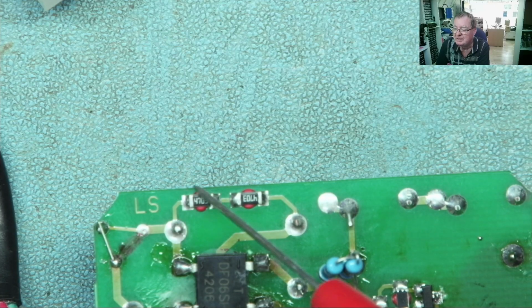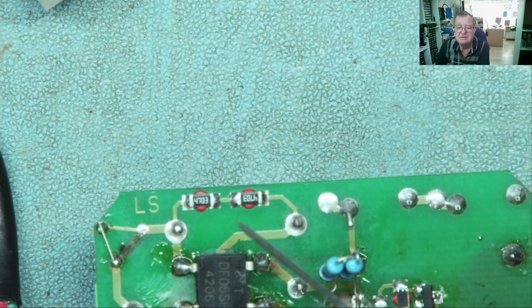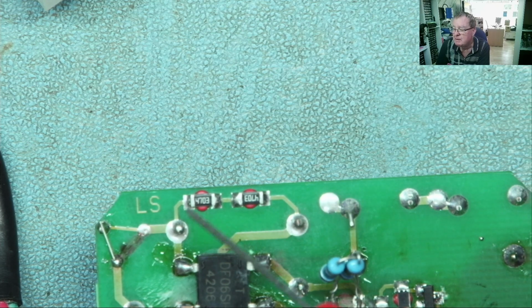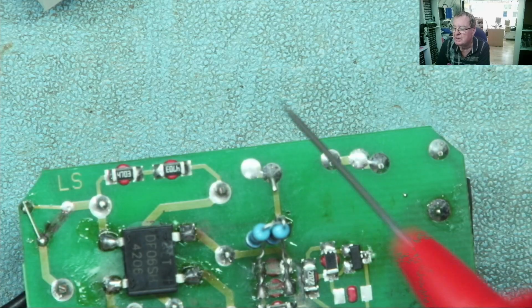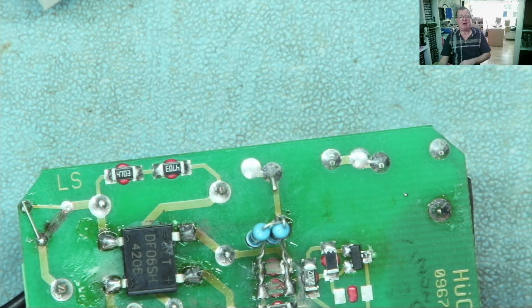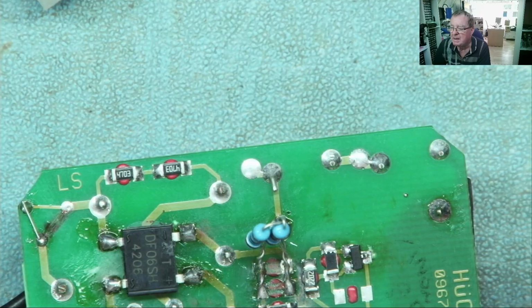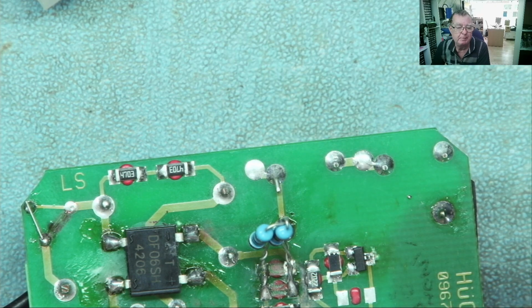So 470,000 in series with another 470,000. So that's 940,000, almost a megohm. And you often find 3 or 4 in series, and they may be higher value than these, 1 meg or more. These sort of resistors in switch mode power supplies are part of the startup sequence, which powers the power supply up when you first apply the mains. And those resistors have a habit of just giving up. It may be intended as almost a 1 megohm resistor, and it now reads 7 megohms or something like that. They don't fail by going low in value. Like any resistor, they go high in value and the power supply won't start.